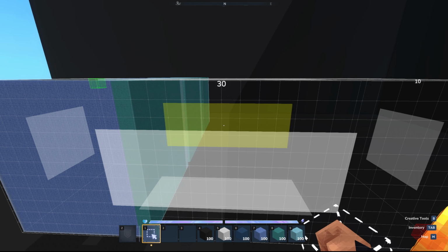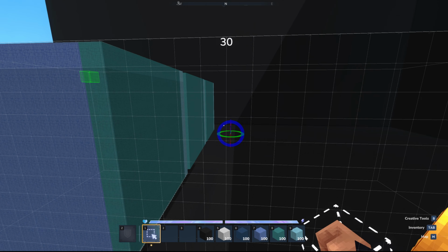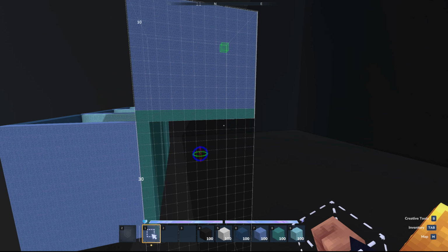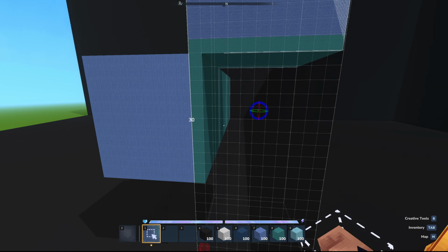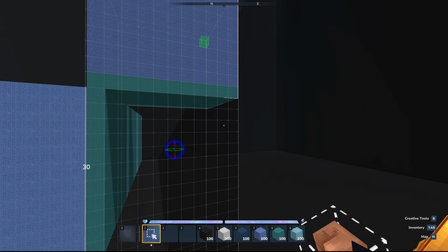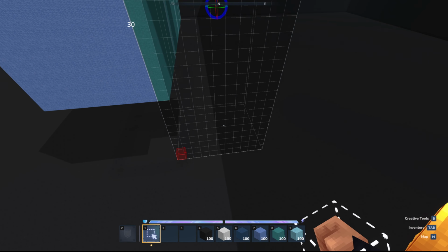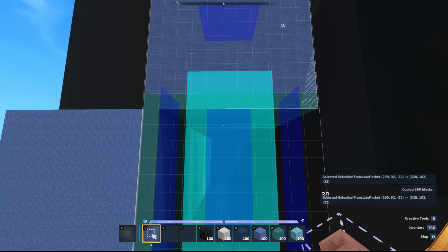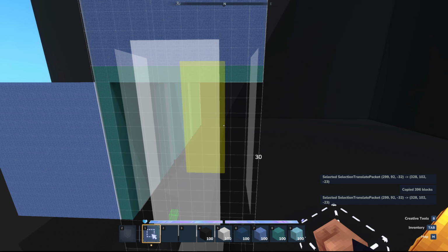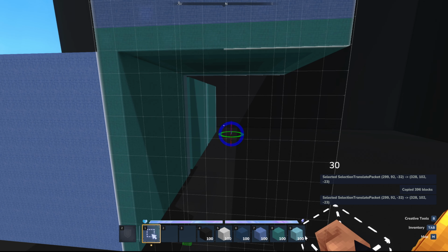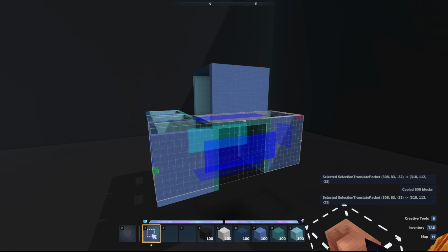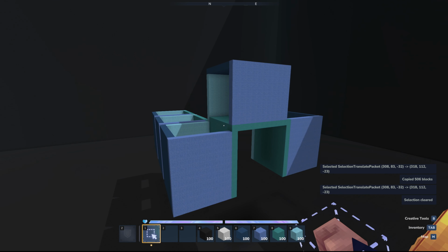So if I press Alt R and rotate now, I can just get the blue and rotate. You will see that we've rotated it counterclockwise, right? So the 10 blocks in the middle are the center of rotation, while you can see the sides are properly shifting clockwise. And so we can do it again, Alt R, get blue, and rotate it. And so that's how you rotate.